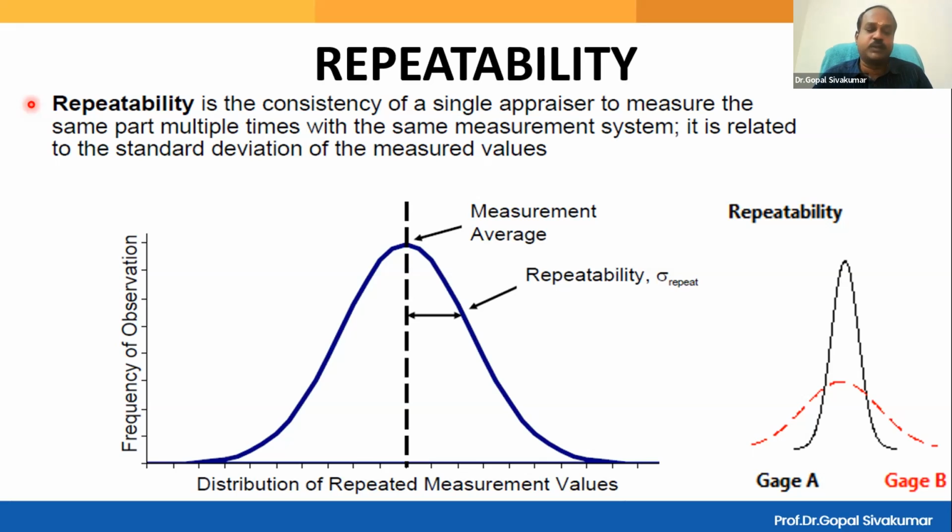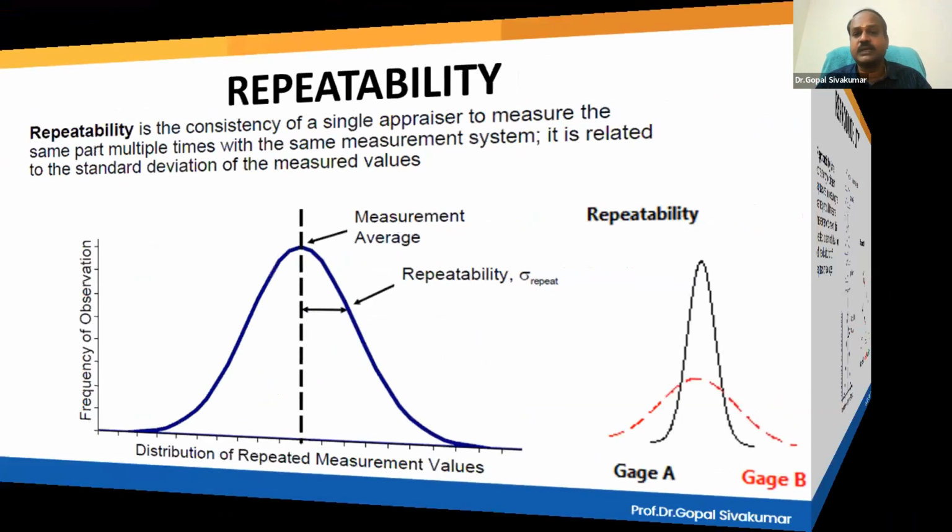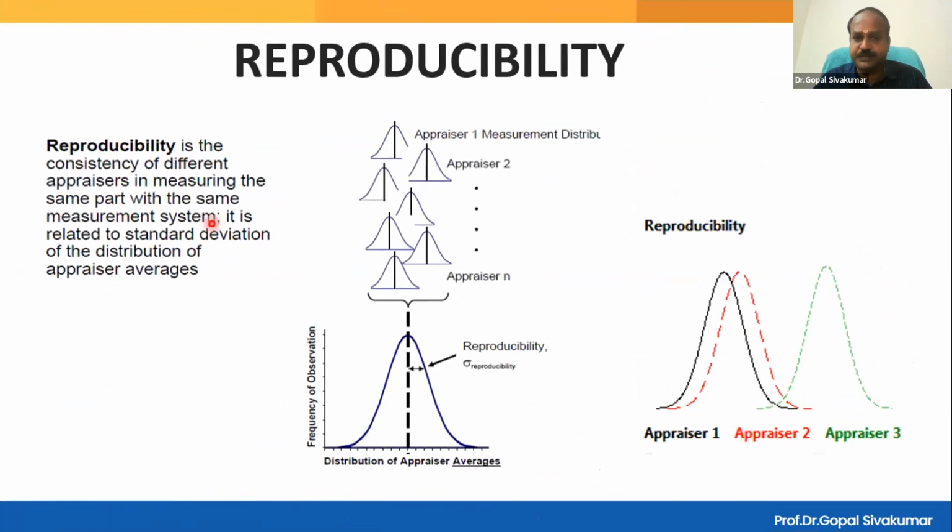When you are asking people to measure repeatedly, they have to be consistent. You're asking them to measure 3 times. They bring 3 different readings. That is not consistent. So there is some variation we can see. In terms of the inconsistency, there are 2 types. One is called repeatability error. The other one is called reproducibility error.